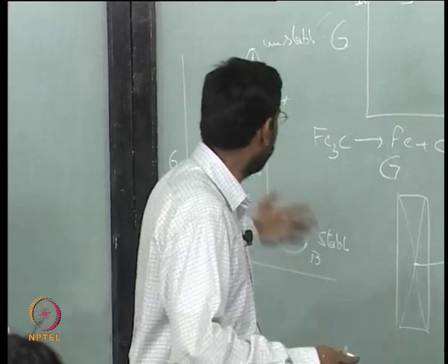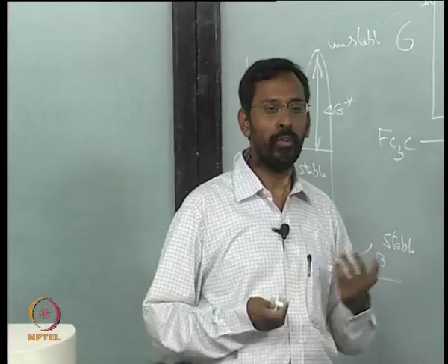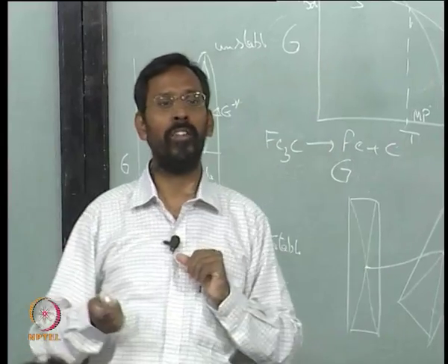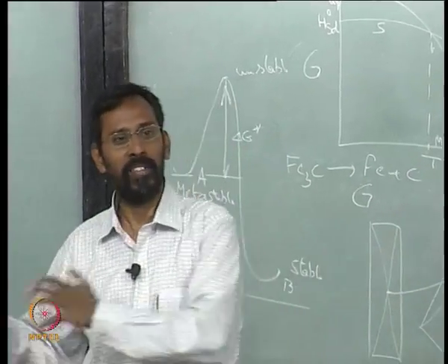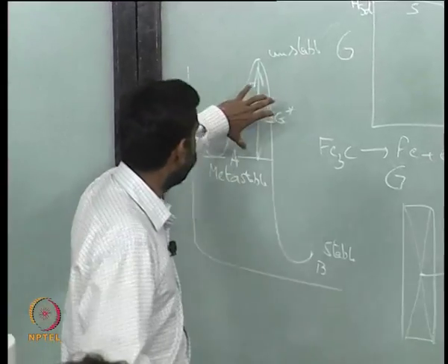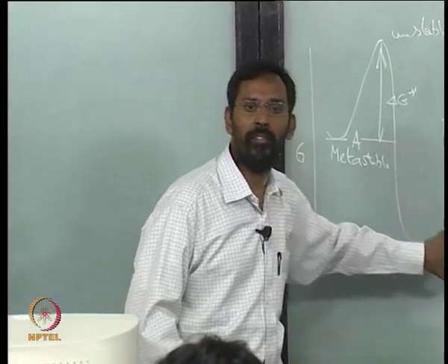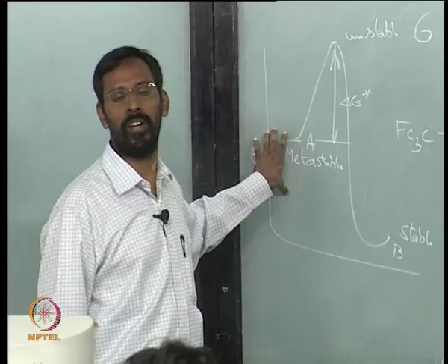Even when people do spheroidization of steels for a very long time, you would see that the cementite spheroids that are forming can even split and you get ferrite plus graphite. People have done this and seen it. So in principle, if you can provide that activation, any metastable state would like to go to a stable state; otherwise it would remain in a metastable state forever.